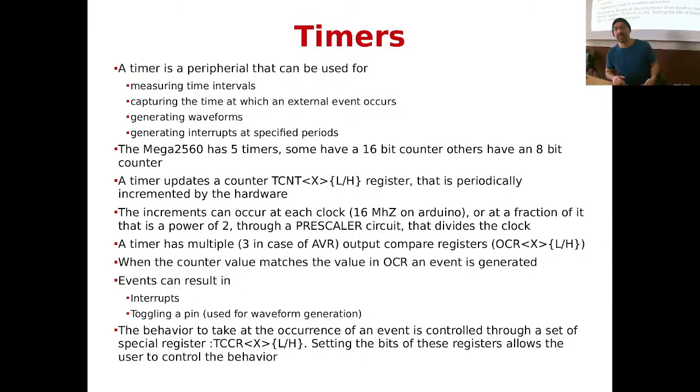And another way we can use the timer, trivially, is to attach the output of a timer and say, hey, dear timer, whenever you reach this number that I've told you, instead of toggling a pin, send me an interrupt. This is another way you could use the same thing. And we have done this just with a thing that counts. It's a very simple piece of electronics, but all this can be done by a thing that says 1, 2, 3, 4, 5, 6. Then when it reaches the end, it restarts 1, 2, 3, 4. Now, on the Mega, you have 5 timers.